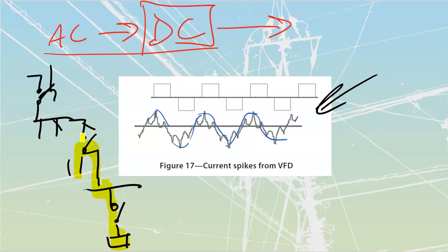All of this stuff is going to be done through the use of proper meters, hopefully. Particularly, you're going to be monitoring what's called THD, which is total harmonic distortion that we have on a system. THD is a measurement of the amount of junk on our system. It doesn't show us the picture of the system because we don't necessarily know what to do with that, but it tells us, hey, you've got a lot of distortion around this frequency or this frequency or this frequency, and then you can also try to filter some of that stuff back out.